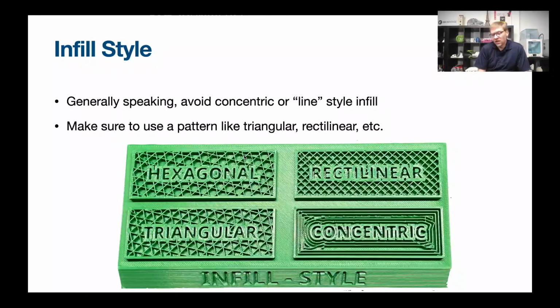Infill style, usually you don't worry about this, just let your slicer pick the default. Usually the default is something like the hexagonal or the rectilinear or triangular, one of those that you see there. Don't choose something like concentric. It might look nice, but it's not as strong, because those lines aren't crossing each other inside.